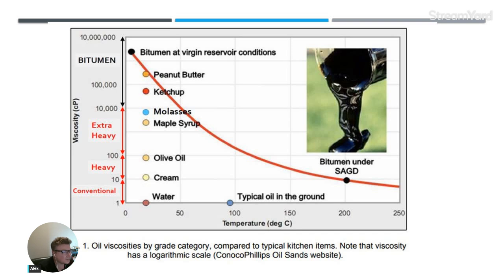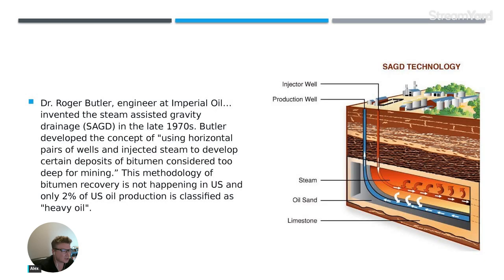So our oil, the bitumen we're talking about, is very viscous. In normal conditions, it's about, I would say, 1 million to 10 million centipoise, and it's really like that across all assets, regardless of what asset it is. It's really hockey pucks. It's giant hockey pucks. So if this hockey puck sits deep on the ground, how can I produce it easily, right? And so the solution is you have injector and producer, you inject the steam, reduce the viscosity, and drain everything